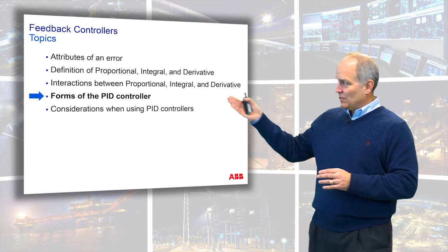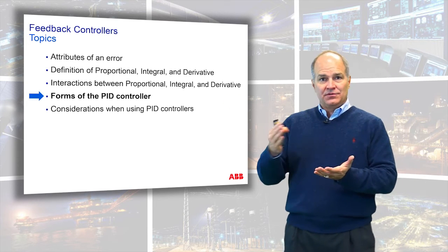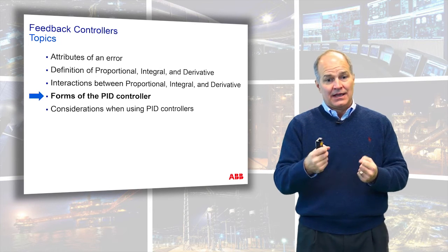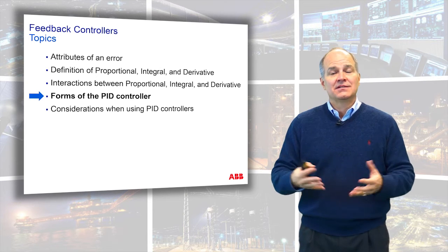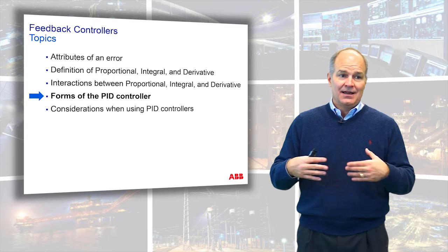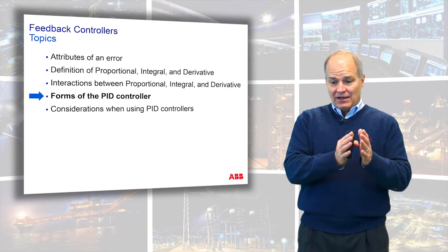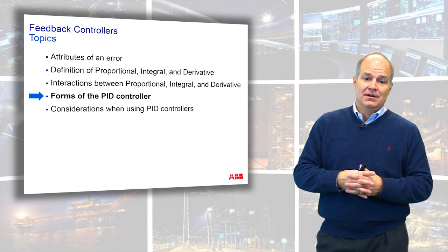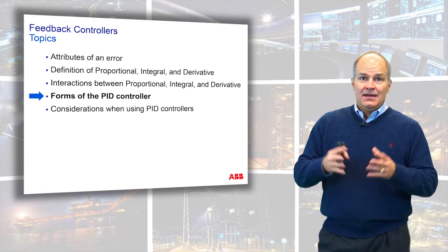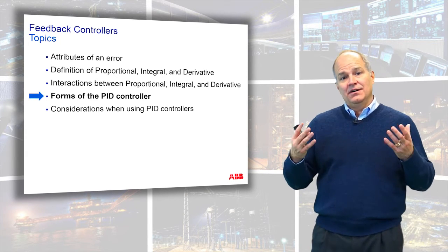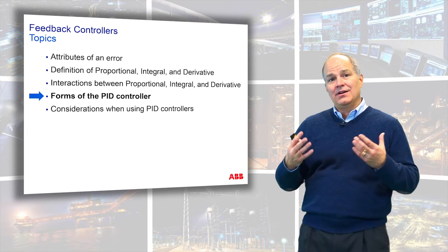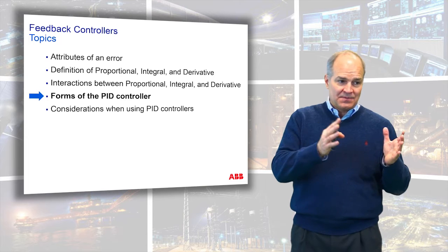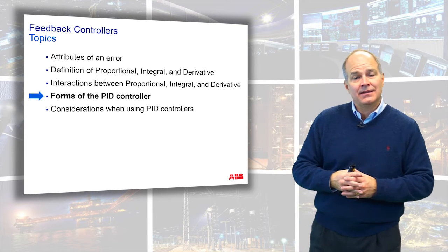It was when we went over the interactions of proportional, integral, derivative that you started to see the power. You got the proportional kick and the integral action, and we introduced this concept of a rate or a reset time or a repeat time. It's how long does it take to repeat the original proportional request. That definition of repeat time really only applies to one of the forms of the PID algorithm. It just makes sense in our discussion to explain it that way.